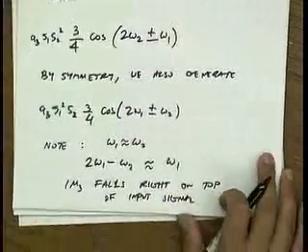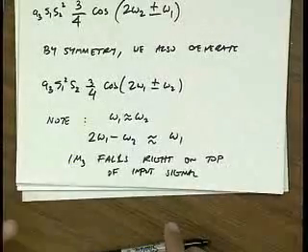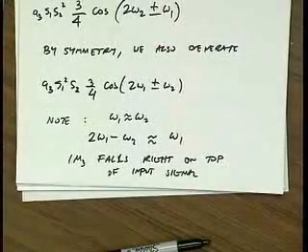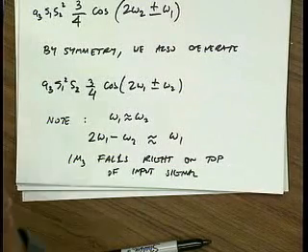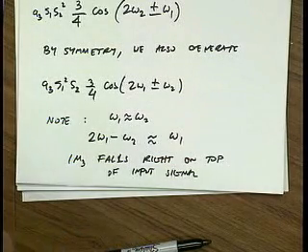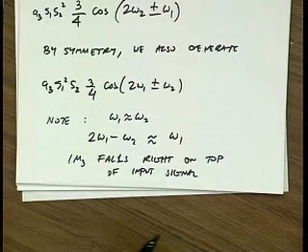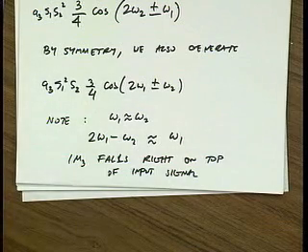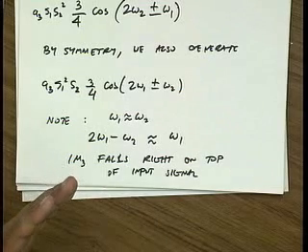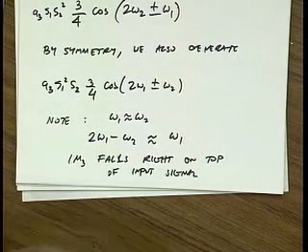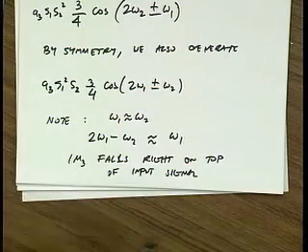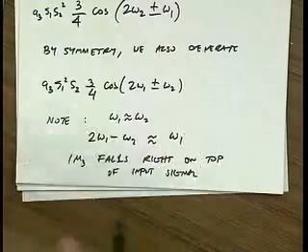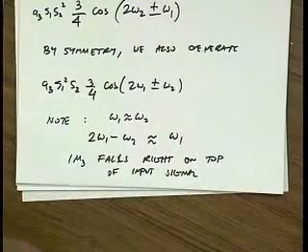In other words, before we had to dream up these weird scenarios where there were these two signals and they were just spaced right and they intermodulated and then they produced distortion, right? That hurt us. Here, we don't have to be very creative, right? The signal is going to interfere with itself. You might say, well, that still requires two tones, but really any modulated signal has infinite number of tones in it. So if I have a modulated waveform and it goes through a nonlinearity, the third order intermodulation distortion is going to produce frequency right in band. So I'm going to create a signal that competes with itself.